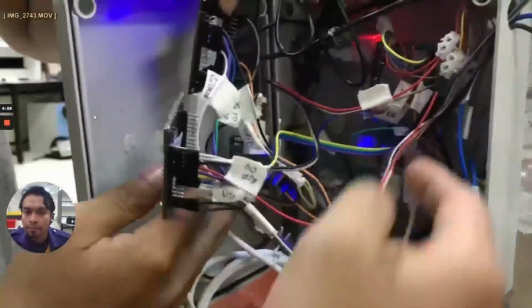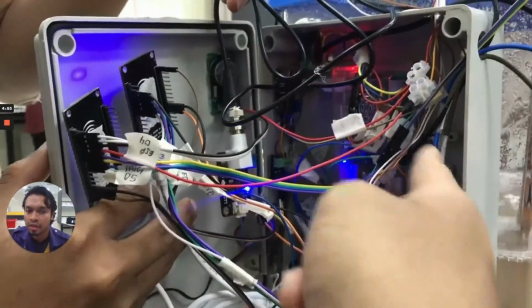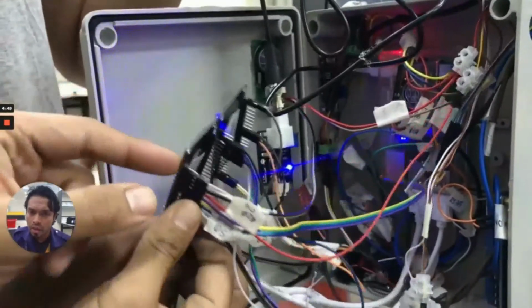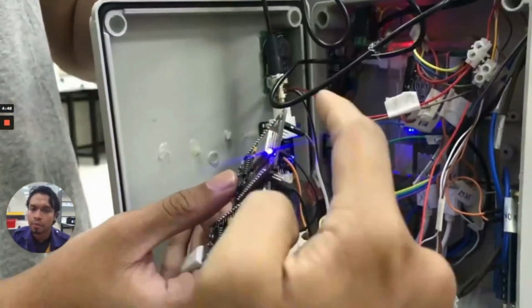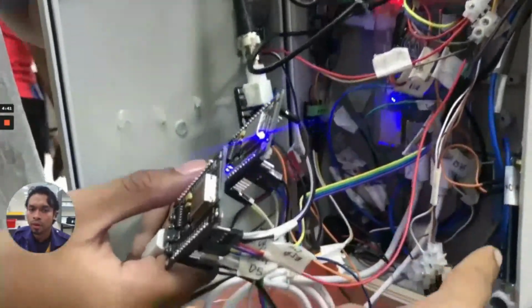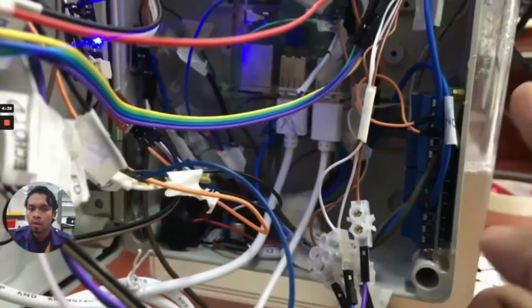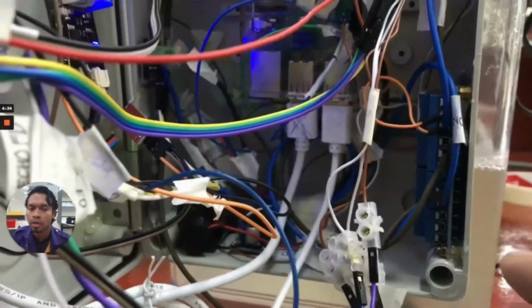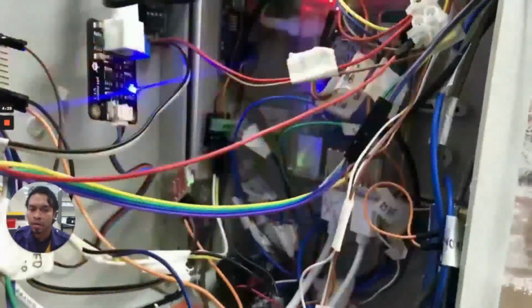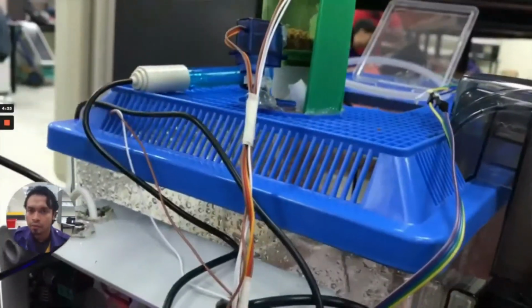For the Raspberry Pi, we use it as a controller to trigger the relay, and then we use 2 microcontrollers. The light blue means transferring data to the Raspberry Pi to turn on all the sensors, and then we use a 4-channel relay, where 2 relays control the motor pump and the other relay controls the LED. The servo motor is used to control the food to feed the fish twice a day.